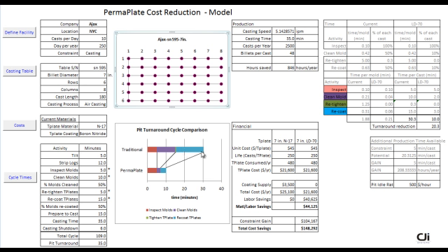It's this savings in time that has the benefit of reducing labor costs, but also increasing productivity. In this scenario, we have a T-plate cost that was put in identically, the same price, the same lives, just to neutralize that. We've reduced the coating supply, so from material and labor alone, we're saving $44,000. Because there was a constraint in casting, we established 5 minutes. We apply the 5-minute savings per the number of casts per year times the pit idle rate of $500, and that adds up to another $104,000, for a savings of $148,000.